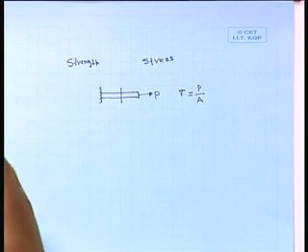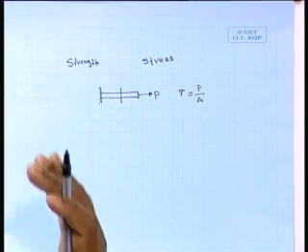So, anywhere we try to get the stress, we can get it by P divided by area. Now, this is one of the very simple cases. In a real structure it may not be so. Stress may vary from point to point. So, our objective is to find out the distribution of the stress and its maximum value.